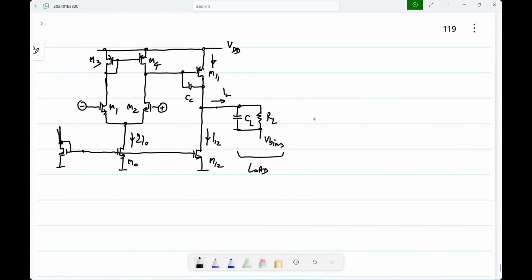Most you can pull out is, yeah. So what happens is that I11 is IL plus I12, right? So if IL is positive, there is no problem. There is no problem in the sense, of course, eventually it will get limited, but no transistor turns off. Okay. What happens is if you keep pulling more and more IL, more and more current will flow through M11.